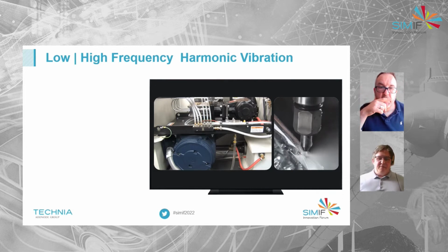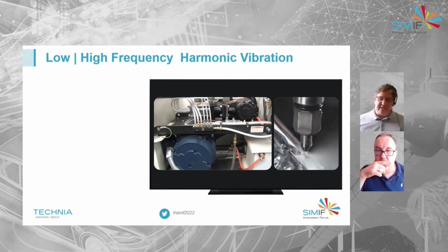Yeah, but then at the same time, coming back to that test that we'd just done before this, if we put dampening in it, that's going to be something that's soft, which allows movement. So what effect is that going to have on that resting state? Is that dampening that we're putting into this going to mean that the nozzle is going to move more because the assembly has got more flexibility in it? So this is where we can experiment and start figuring out where that balance of vibration versus rigidity comes in.